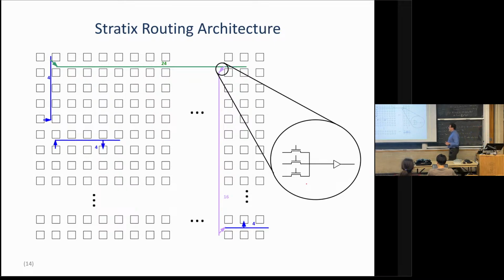So I can't remember if we did it in Stratix, but we did do that for the long wires in some of the later generations. I'm not showing that in this figure because it's kind of a detail. It is effectively, you can think of it as a length 0 wire. Like just basically you have the mux, but the mux doesn't really go anywhere except to other muxes. But it serves a similar purpose of sort of giving you more ability to collect signals so that more of them have the option to get onto some expensive resource.